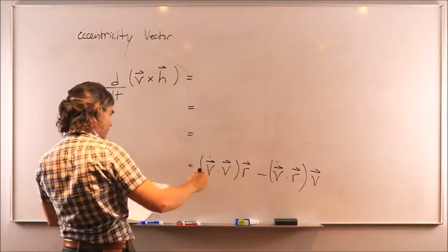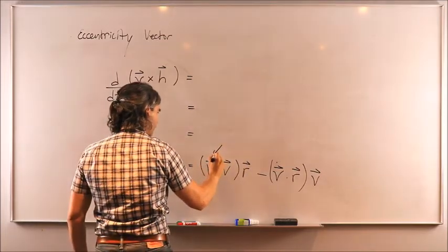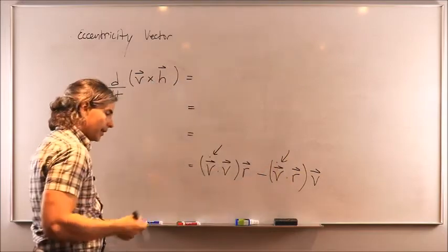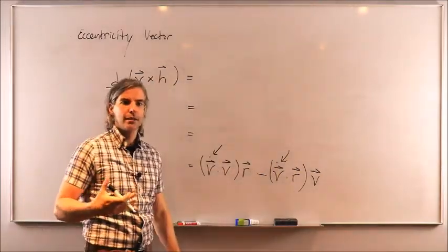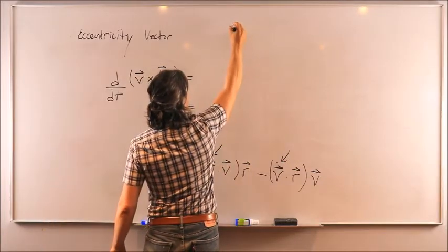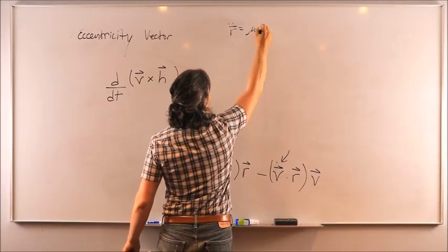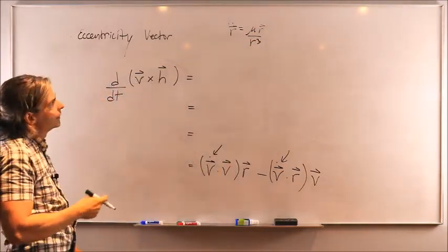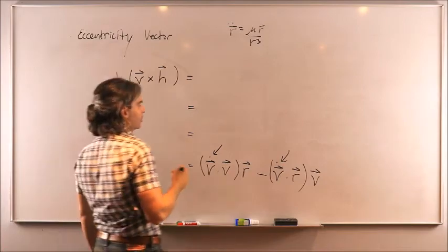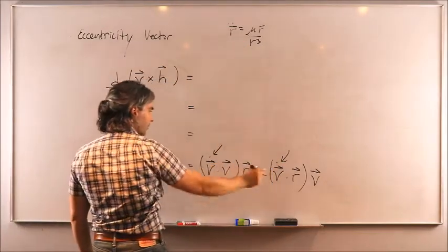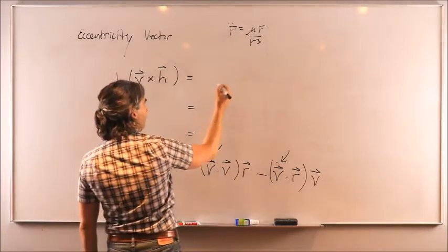So if you look at that equation, we have the v dot term here and there. What is v dot? Well, again, this is our inertial acceleration. And we know that our inertial acceleration is our two-body equation of motion, correct? That's our minus mu times position divided by the distance cubed. So I'm just going to substitute that expression for my v dot terms in that equation and see what we get.